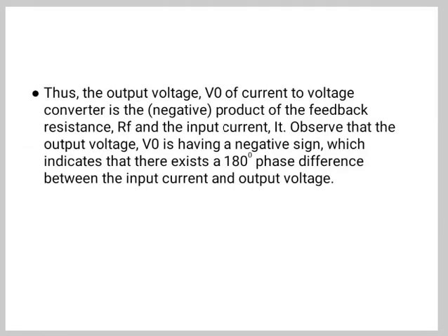Now if we apply KCL, that is Kirchhoff's current law, to the node at V and the input current to the inverting input, Vi, then (V out minus V) by Rf equals Ip plus I. So the output is connected to V through the resistance Rf, and the op-amp is in negative feedback configuration.